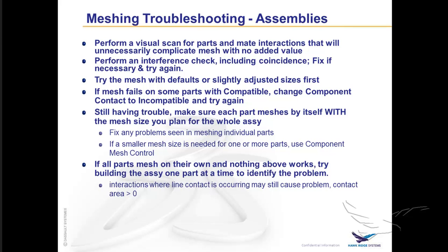And just a word of caution here about contacts. The contact area should be greater than 0. So you don't want the point of a cylinder contacting a face, or a line contact between a circle tangent to a planar face. You want to try and avoid those things.